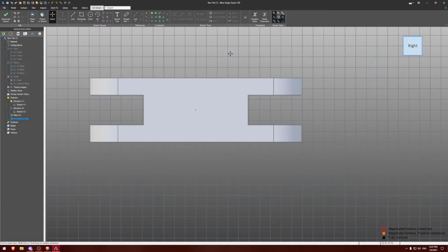This part could be a little bit tricky. We're looking at a radius of 40 for this kind of outer bit here. Let's do another one, 40. They're being automatically constrained, which is perfectly fine because that's what we'd like. Vertical those and these, but not with each other, though they can be, actually. We can horizontal these. Okay.